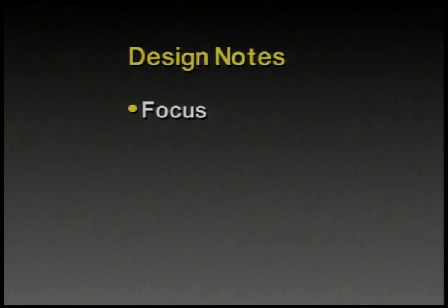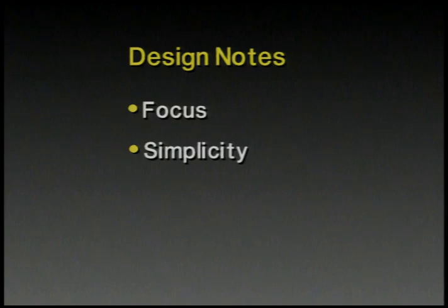So finally, let's look back and extract some important design guidelines from the material that we've covered. First, it's not worth doing a special purpose machine if it doesn't have a special purpose. Recall that we carefully described a simple processing model for three-dimensional graphics before we considered special purpose architectures. It's important as the design progresses to stay focused. Don't end up solving a general purpose problem with a special purpose machine. Given that, however, it remains true that the best special purpose machine is the simplest one that will do the job. A Rube Goldberg contraption that precisely matches a specific task is never the right answer.